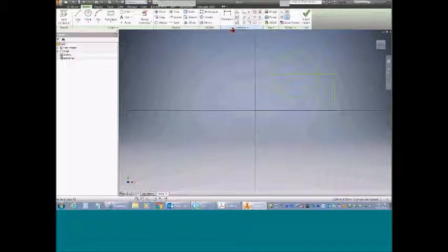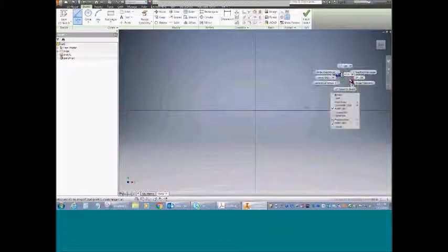And I could start dimensioning this. My circle's already in the middle because I latched it to the midpoint here. So I start applying some dimensions. I'm not going to take the time to do that. And then I could extrude the shape that I want and get this kind of half moon shape in there. So for sure, that's an easy way to do it. I'm going to undo that. But the goal of this lab is to really start getting them thinking about the individual pieces of geometry. So I ask them to do it in that fashion.